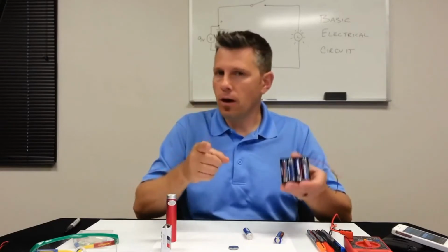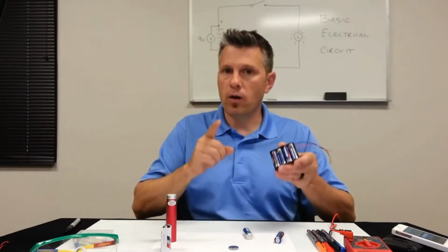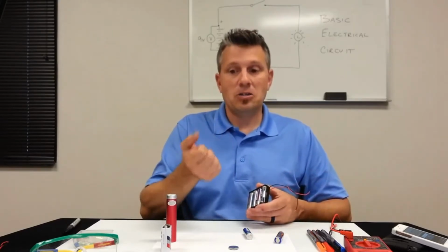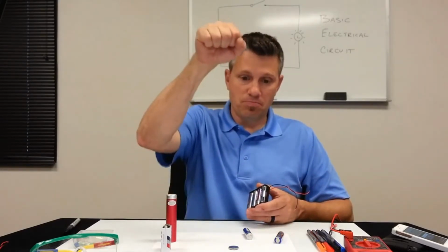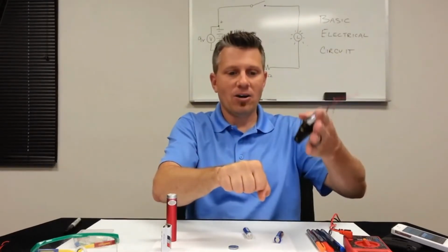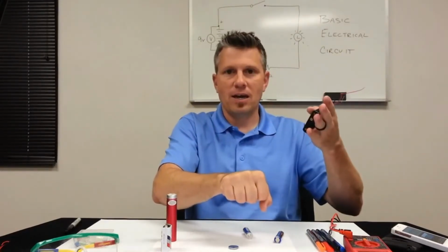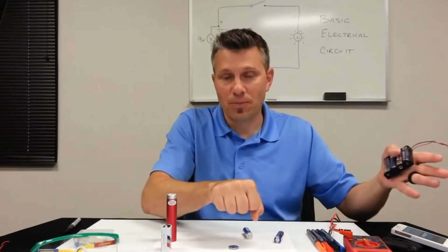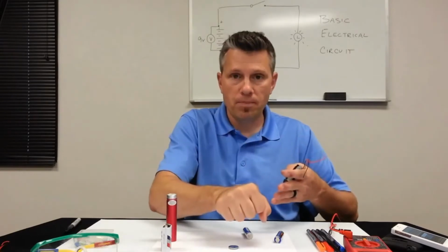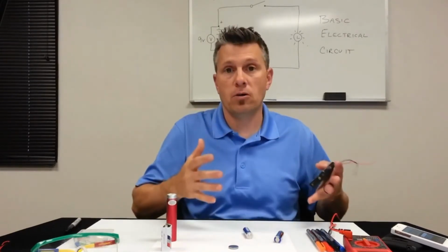Now the battery in your car also has 12 volts. It's much bigger. And if I took a metal wrench, and I do not recommend this, but if I arced the positive to the negative side, I'd be in some serious trouble. What would happen is, at the minimum, it would probably burn me, and it could kill me easily.